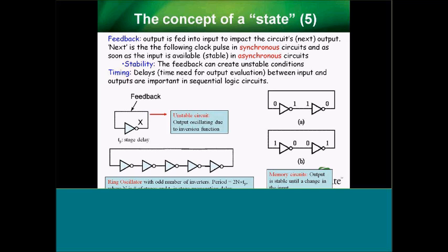Well, you can do the opposite there. If you put two inverters, then basically you've got a very simple, stable feedback loop. And I tell them there's something else you can do. You can make a ring oscillator. It's unstable, but it can be done. Real ring oscillators are more complicated, but you can take a bunch of inverters and, if there's an odd number of them, then for all of those little gate delays, whatever 20 nanoseconds or whatever it takes to get through these gates, you add them all up and you've got that time high, that time low, that time high, and it oscillates between the two, and you've got yourself some sort of a cheap clock, kind of.